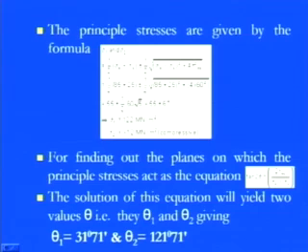So you see here, now come to the real formula which we discussed in the 6th chapter, that the analytical solution always gives you the value of the principal stresses where the shear stress is 0. Or we can simply calculate the sigma 1 and sigma 2 value if you know the value of sigma x, sigma y and tau xy.